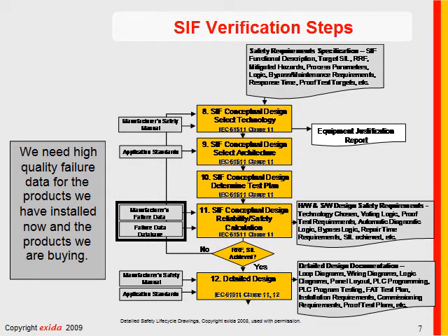In the middle of the safety life cycle, when we have chosen our particular equipment, our level of redundancy, and our test methods, one can perform a reliability calculation to show if any given design meets the risk reduction criteria of the specification. That's the essence of the performance-based methodology. And I can honestly tell you, it was quite controversial when the standard was first written. And many of you know it remains quite controversial today.